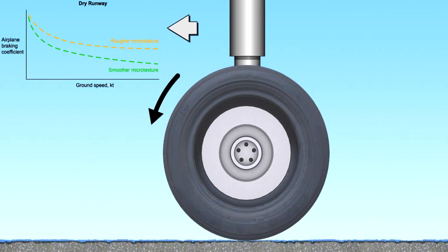The most positive method of preventing this type of hydroplaning is to provide a microtexture to the pavement surface which breaks up the film of water, allowing it to collect into very small pockets. This means that the tyre footprint will sit on the peaks of the textured surface as shown, and not the film of water.